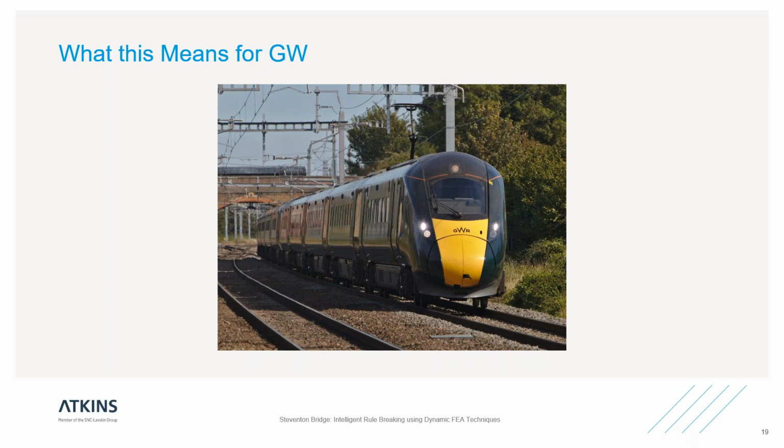And Network Rail is expecting to see increased wire wear on this steeply graded section, and they're expecting to see related additional maintenance related to those higher forces. So for that reason, Network Rail are now undertaking a detailed wear measurement through the whole graded section every 6 months, with an aim of better understanding what the wear rate is now that we've got multiple pans per hour going through the bridge.